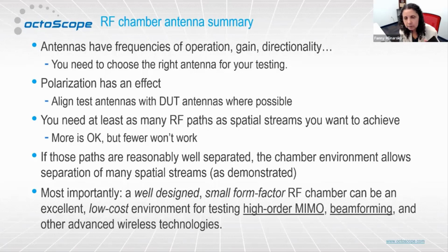If I may jump in, the question could also mean another thing. In a small device like a phone, your antennas are necessarily close, so it's going to be hard to send two different streams because, being close, they will hear the same thing. If spatially they hear the same thing, you cannot send two streams, but what you can do is cross-polarize them.